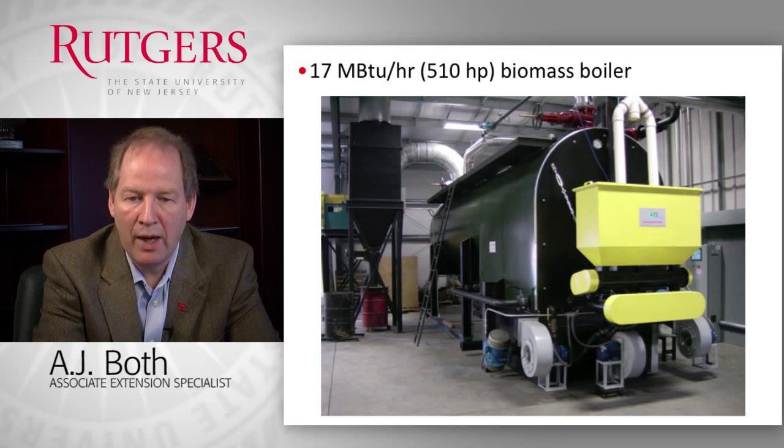So you see the white pipes on the top right hand side of the image delivering the wood pellets into an auger system, a hopper system, that then delivers a certain quantity of those pellets into the combustion chamber, and then the fire heats the pipes, the plumbing surrounding the combustion chamber, to generate hot water that we then pump throughout the greenhouse.